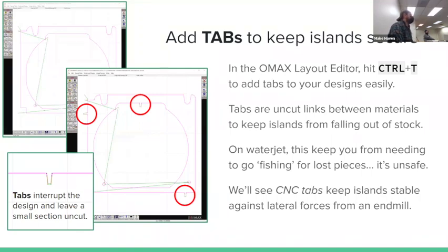It'll cut the metal too. You adjust the rate that it cuts at. So if it cuts fast enough, it goes through the glass, but not the backer. You can sort of do that. It can still go awry if enough water gets under there that it blasts it up. So it's not perfect, but it has some workable solutions. Tabs are the nicest way to do it. And tabs in metal, super easy breezy, because you twist and cut and then they're gone.